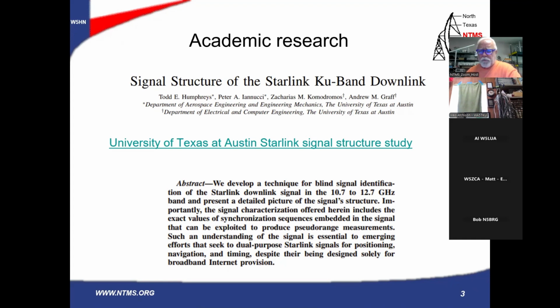Importantly, the signal characterization offered herein includes the exact values of synchronization sequences embedded in the signal that can be exploited to produce pseudorange measurements. Such an understanding of the signal is essential to emerging efforts that seek to dual purpose Starlink signals for positioning, navigation, and timing, despite their being designed solely for broadband internet provision.